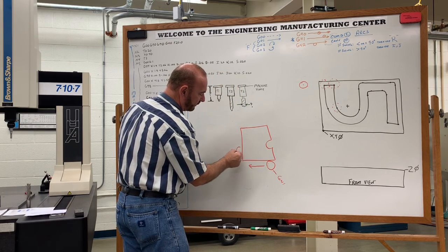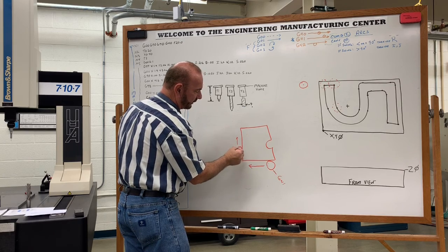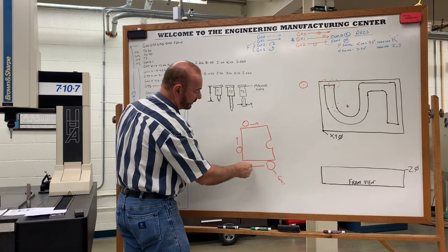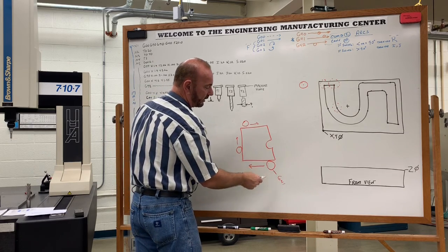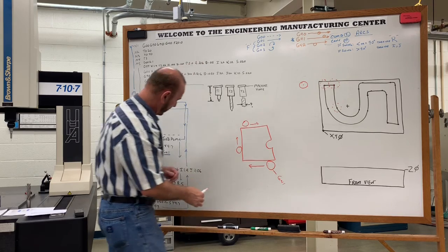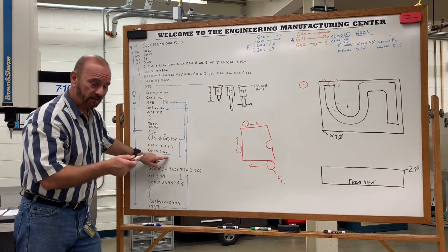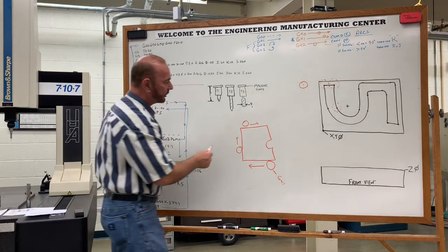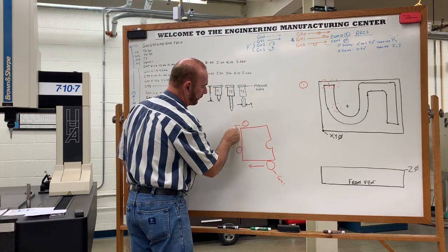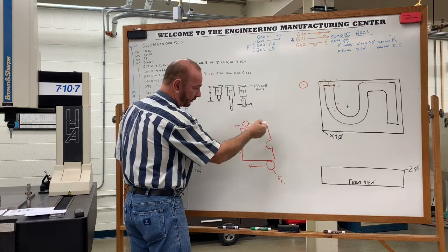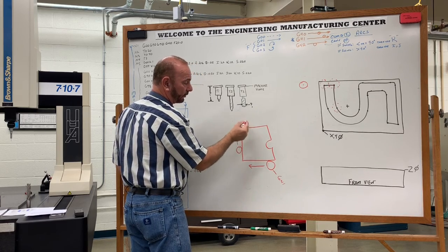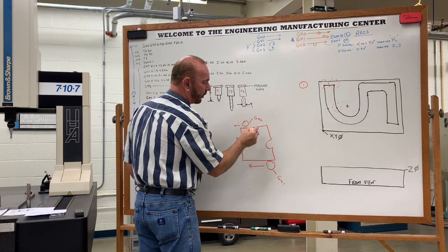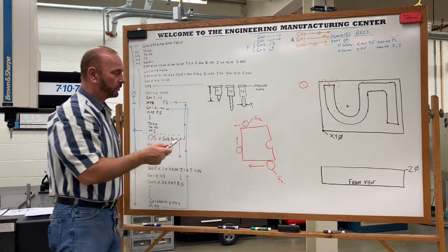As he moves this way, in this direction, he's still on the left. And when he moves this way, in this direction, he's still on the left. So as long as he continues to move in the same direction, the cutter compensation remains the same. Once it's turned on like a light switch, it does not need to be repeated in every single line. If we were to change this arrow and move it to this direction, now, remember, you're the cutter looking in the direction you're traveling: what side of the part are you on, or the line you're cutting? Now we're cutter right, and this is G42. That's called conventional cutting. And there's a reason why we use either of those.